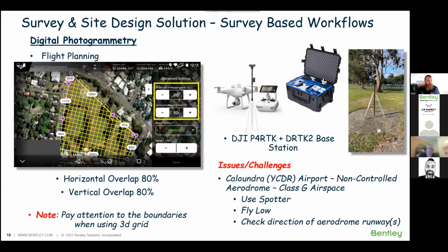So this is a little bit more of a continuation of our flight planning. You'll see our overlap for both vertical and horizontal is set at 80%. So this is to ensure there is enough overlap to stitch the images and create the visualization.